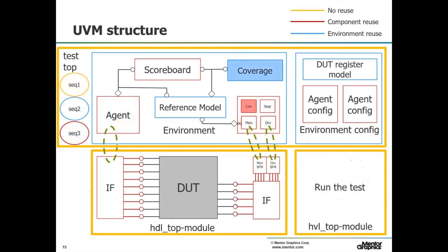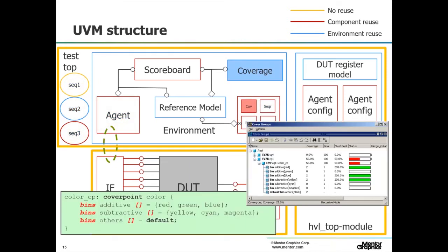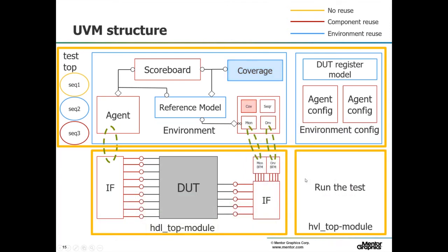The other things, maybe we have a coverage collector, and that's going to be our SystemVerilog cover points, our SystemVerilog cover directives, cover assertions, all these different coverage objects that we can collect metrics about how well covered our device is with the coverage things.